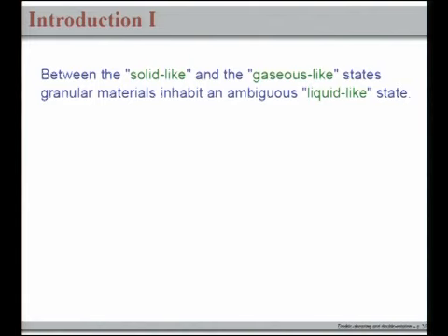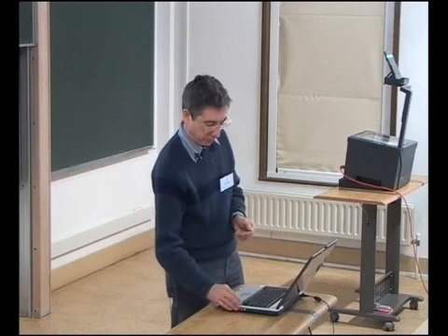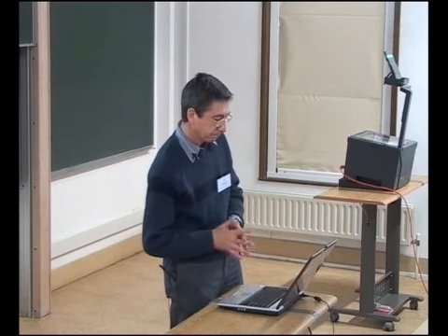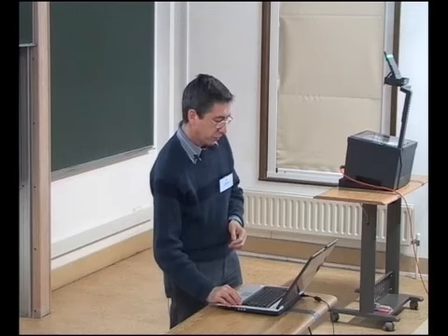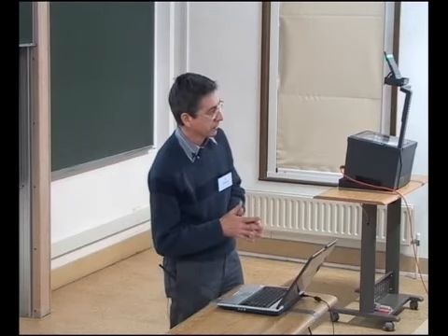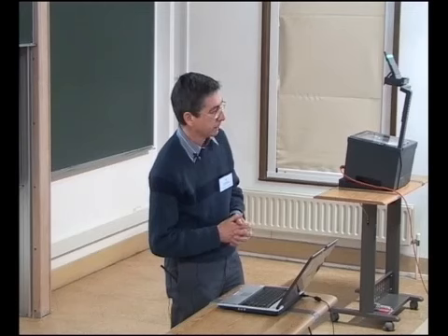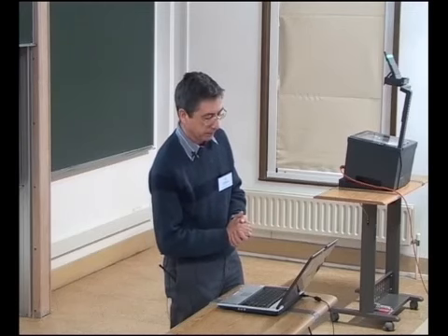Maybe this is more ambiguous, not quite easy to define. Plasticity models occupy a middle ground between a nice, definite, solid-like elastic model and the more gaseous states. So where is the dividing line? I guess the dividing line is that the constitutive equation for plasticity models is rate independent, and for fast flow it becomes rate dependent.